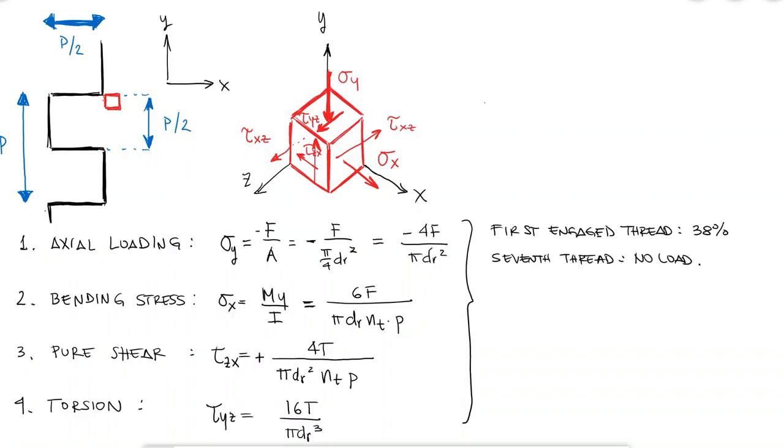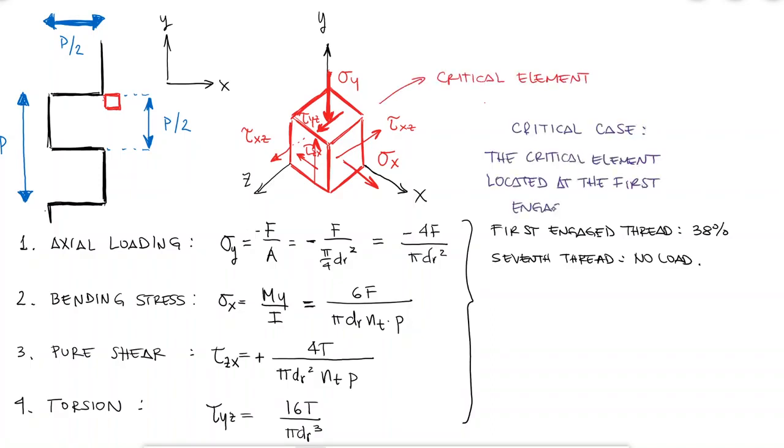This is useful to us in that when we're designing a part that needs to be threaded to put a screw through it, as a rule of thumb, more than 6 engaged threads will not make the joint safer. It is also useful because we can estimate those stresses for the critical case, which is the first engaged thread that carries most of the load.